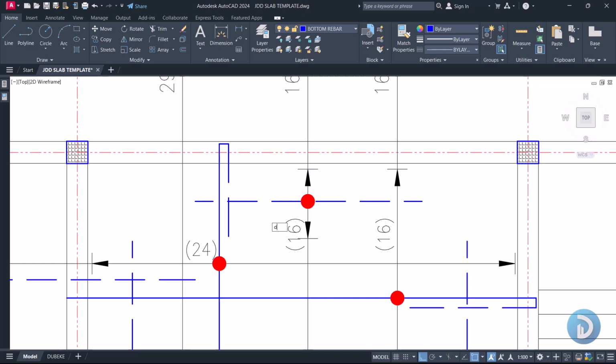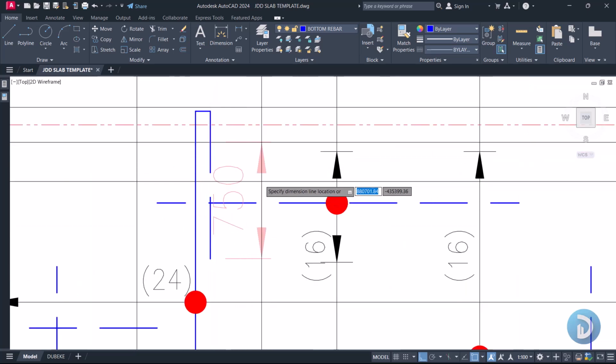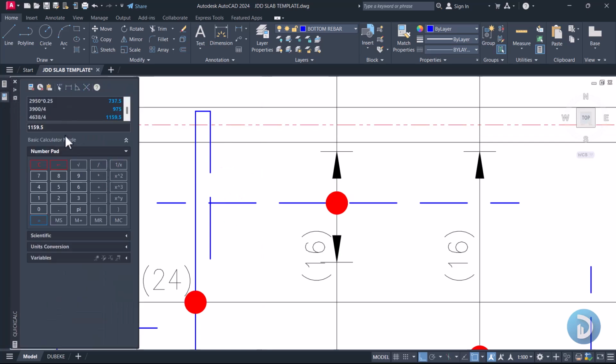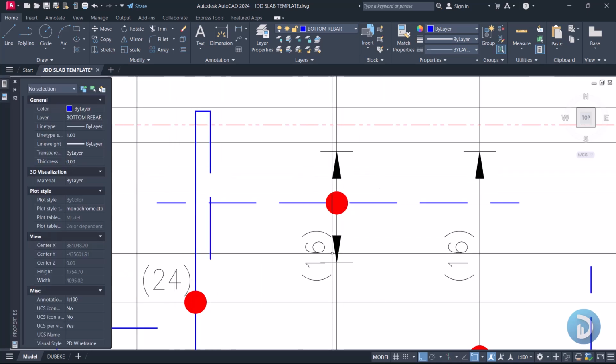All right, then to get our total numbers, we just have to dimension this, since we are also using 200. So this is 750 by 750 millimeter by 4. Then we have what, sorry, 750 by 200, we have what, 3.75. So that leaves us at what, 4 numbers of reinforcement.